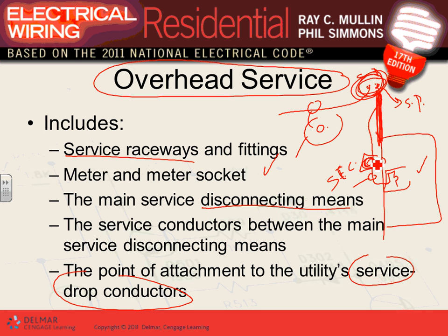But when you talk about service, that's what you're going to ask yourself: where are the service points? So Derek, when you become a big engineer and they give you a hospital and say, now we want you to design the power system for this hospital, the first question you're going to ask yourself is, okay, what type of voltage do we have? So talk about the utilities right here. Let's go see what type of voltage. You're talking about the service coming to your building. Okay, are we coming underground or overhead? Do we have overhead conductors or underground lateral conductors?